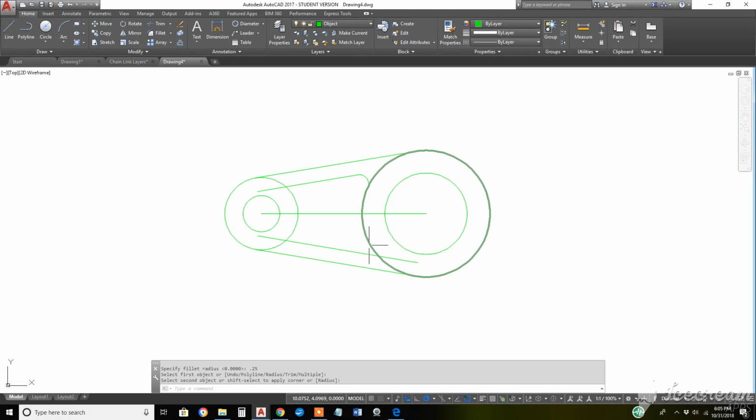Click in the vicinity where you expect the arc to stop and start, or it won't appear the way you expect. Click fillet again, click where you expect the arc to be on the circle and on the line, and it'll appear as you're expecting. Click fillet, hit enter again to invoke the last used command. There's our 4 fillets.